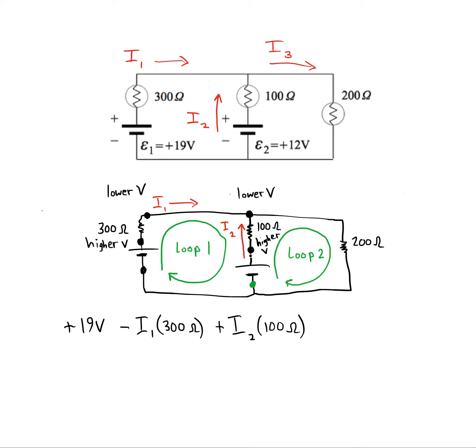All right, now we're going to go through a battery, but we're moving through in a way that's not conventional. So we're going to lose potential there. According to Kirchhoff's loop law, these four changes in potential have to equal 0. As you can see, we've developed an equation of two unknowns so far, so it alone cannot be solved. We need to use more information from the circuit in order to solve for I1 and I2.